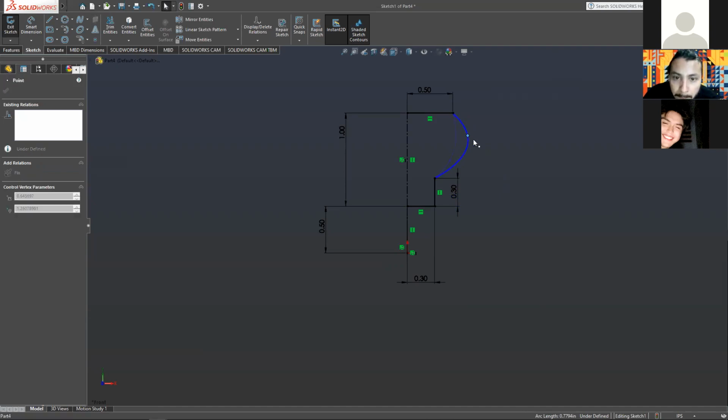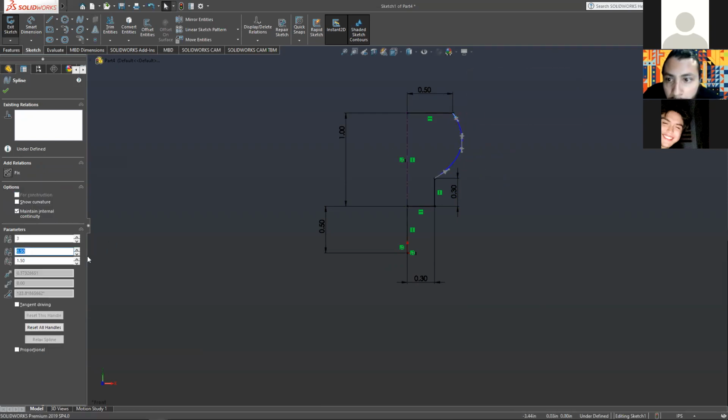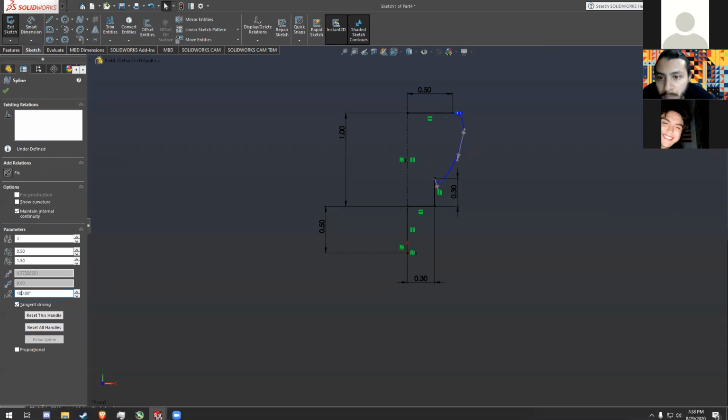So splines, you can mess around with them a lot. You can make weird shapes. They make things look more organic. And you can add as many points as you want, really. We'll do the whole spline tangent driving again, and set the whole 0 degrees. And this is what I was saying, it's all relative geometry with these spline tangents. Sometimes it will invert itself when you hit 0. When that happens, just change it to 180 like I did here, and bam.